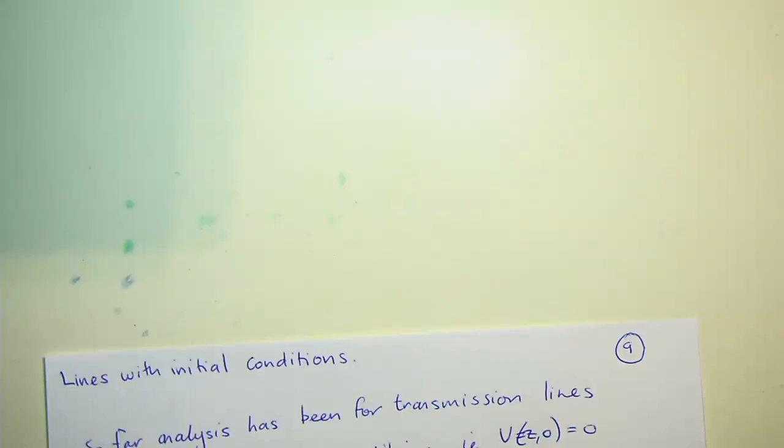So far, what have we done? We've done steady state analysis, and we've done some transient analysis. With the transient analysis specifically, we started off with uncharged transmission lines, where there was no voltage and current travelling on them. Or you can think of circumstances where you might have a logic circuit feeding a transmission line and it's kept at a particular voltage. So you've got a transmission line, the gate or the output is high, so you've got a particular voltage and current on that line. What we want to do is understand what happens under those circumstances and how we would analyze that particular complex system.